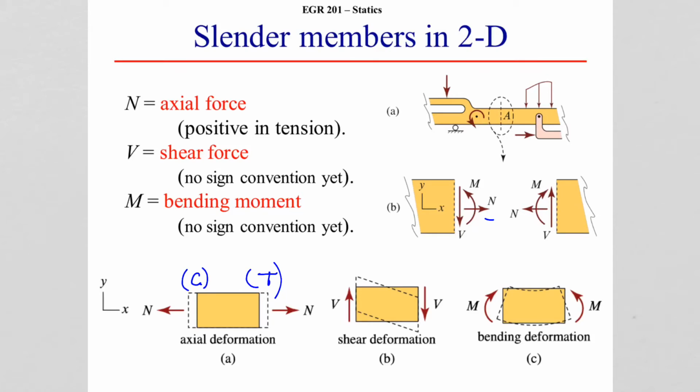Shear essentially makes the beam want to skew. You can think of taking your textbook, putting it on the table, and holding the bottom of the book stationary, and then pushing real hard on the top cover of the book. You will see that it will want to slide, and you'll get this sliding action between the pages. That is a shear force that's developed between those layers of that book, and that is due to this force that is, again, parallel to the cut surface.